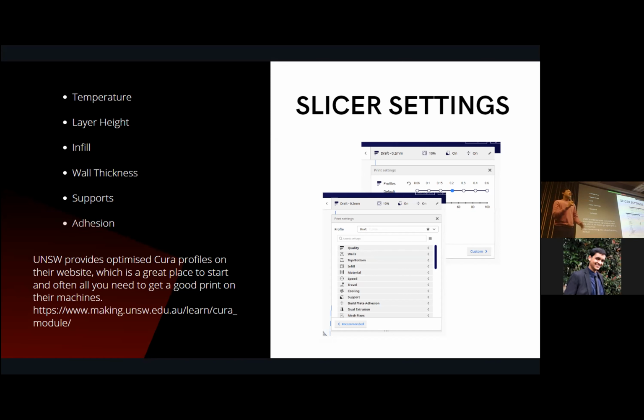I don't really have the infill patterns out here. It would be nice if I could show you. There's a bunch of them, but as you can see here, you can adjust the amount of material compared to air that's on the inside of the print. Increasing that means the lines that make the infill are going to be more dense, and decreasing that will make it less dense.